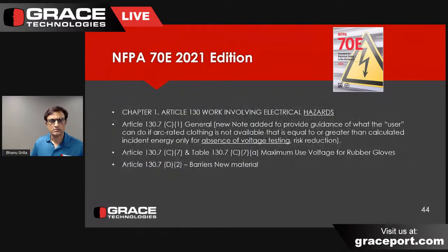There's another issue there, which is, again, if you don't have the outerwear, like this rain jacket, tested in the lab with the clothing you have underneath, which could be an arc rated coverall, you can't add the ATPVs, right? So you need to wear clothing that's greater than or equal to the incident energy. And if you wear an outer garment for weather, as an example, it needs to be arc rated, but we aren't relying on that ATPV because you cannot establish a total system arc rating unless you get the rainwear fabric tested in the lab with the jacket or pants. So that's just another comment.